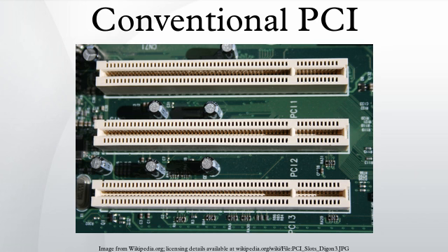PCI Command Codes. There are 16 possible 4-bit command codes, and 12 of them are assigned. With the exception of the unique dual address cycle, the least significant bit of the command code indicates whether the following data phases are a read or a write. PCI targets must examine the command code as well as the address and not respond to address phases which specify an unsupported command code. The commands that refer to cache lines depend on the PCI configuration space cache line size register being set up properly. They may not be used until that has been done.